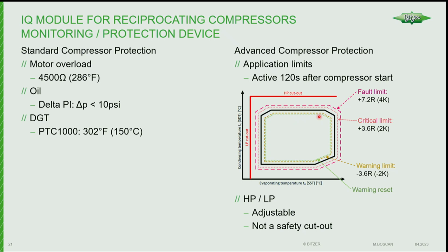A lot of people think that's high, but the difference is that we're measuring right at the compressor, and it's an insertion type sensor, so it's right in the discharge stream. It's not strapped onto the pipe 6 or 7 inches away from the discharge line. So that's why it's higher than what you might think. A lot of times if people call in, we'll say 250 degrees on the discharge pipe because you're measuring on the pipe, not inside the compressor. But this is measuring inside the compressor, so we use that value.